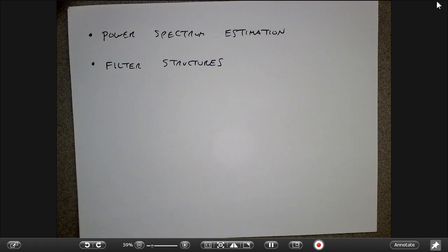If you get down to the nitty-gritty, and you have some noise in your signal or in your filter, different ways of implementing the filter have different implications for how that noise gets amplified in the system. So it turns out to be important in some real-world systems to decide how to implement the filter once I've designed it.